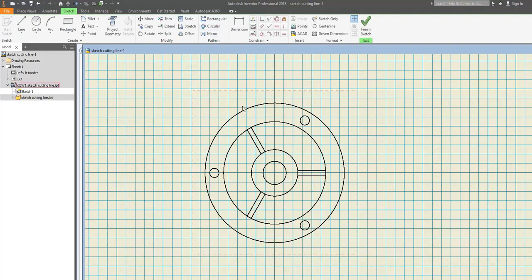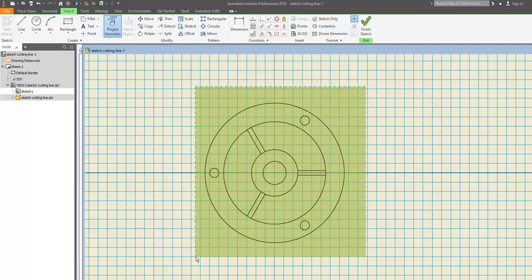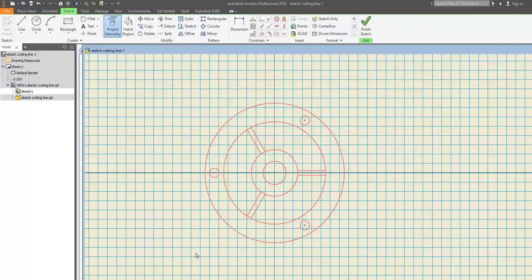Take the image to sketch mode. In sketch mode, to be able to take advantage of indicating some characteristic points, to which the cursor can snap, and also to make the hatching button active, apply the project geometry process. Okay, click on this button, and using the windowing method, have the projection, and then the rest. Draw the necessary sketch lines, and after trimming to remove the unnecessary parts, have the edge of the cutting plane.